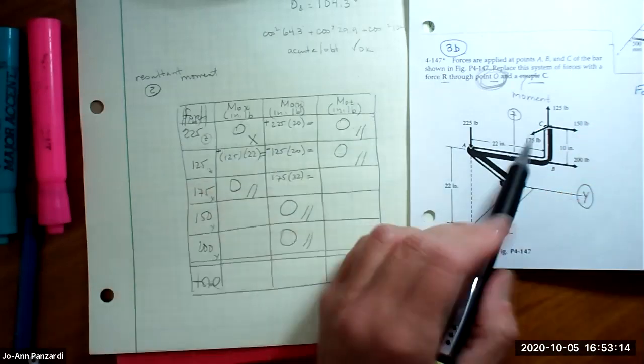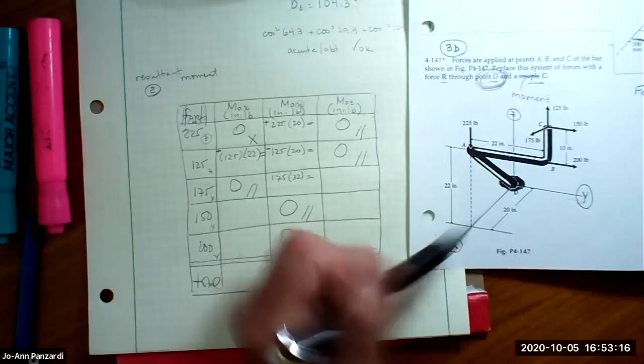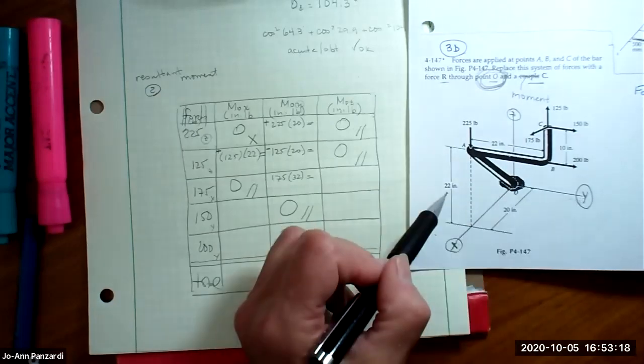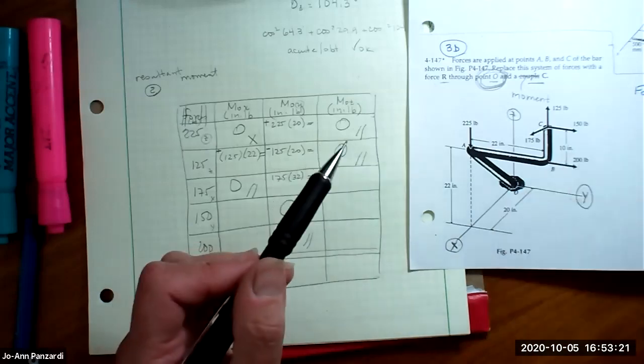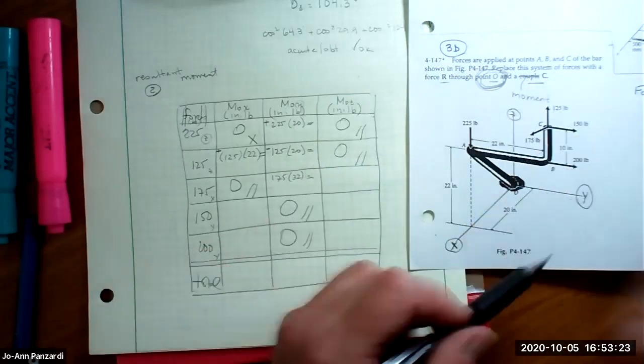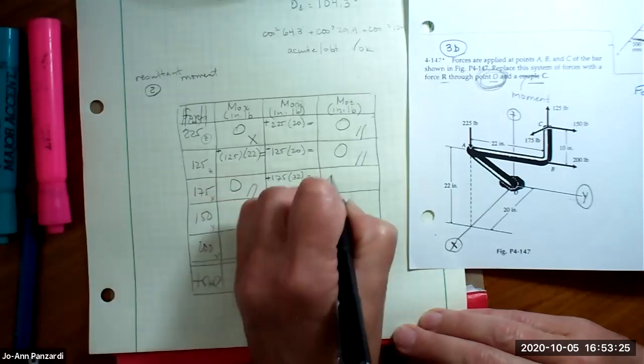And does that make sense? If the 175 is in the x, I'm trying to find the moment in the y, the distance is going to be in the z. 175, fingers go in the direction of force, palm goes towards y, I got a positive. Next,